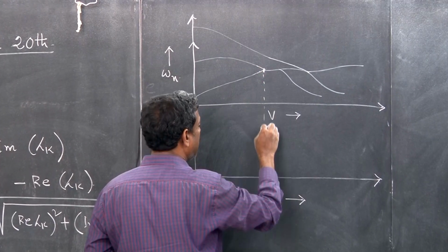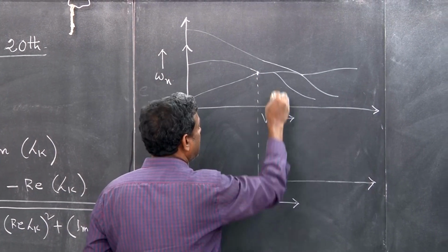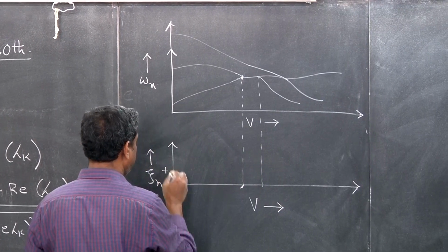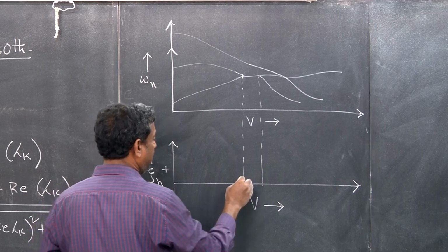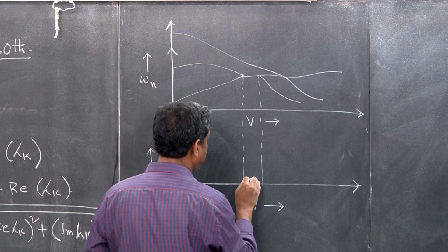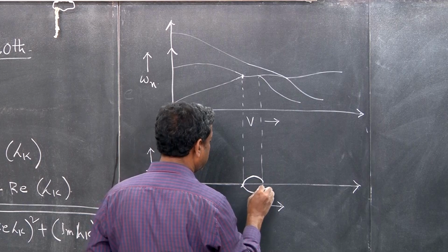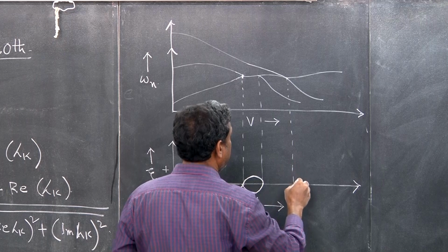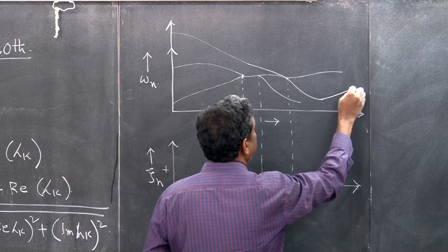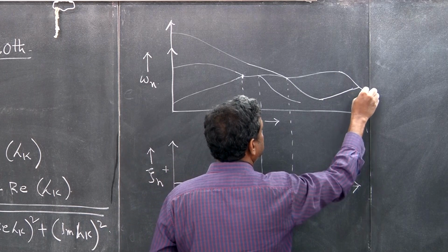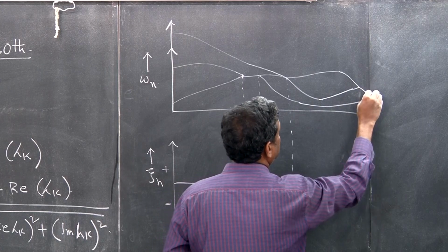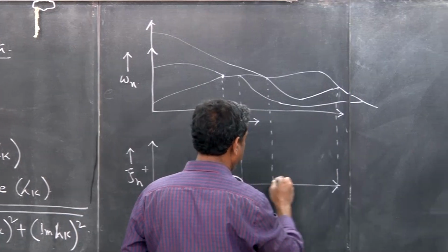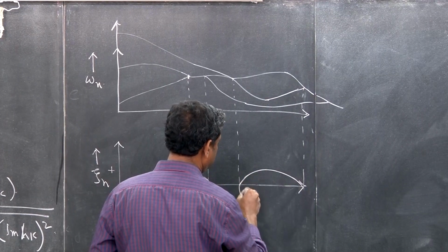Coalescence of this is indicated here, and then between these two, this is the positive damping and this is negative damping. Okay, negative. So here they will go and then ultimately they will have this kind of circular kind of thing, and then once again from here to here there is nothing. Okay, and once again maybe these two will coalesce, then you see there's another flutter happening over there. So here also there will be this kind of thing.